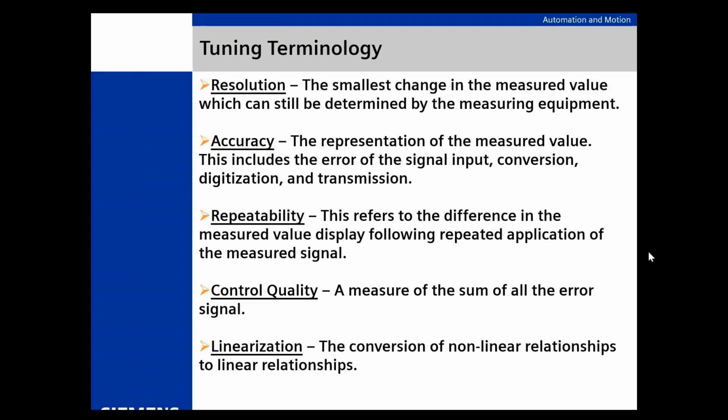If the flow meter tells me this is 400 GPM, and it might not be 400, but that same amount's always 400, I can tune around that. We all understand that a repeatable signal is going to give me the best control for your loop because it's constant.